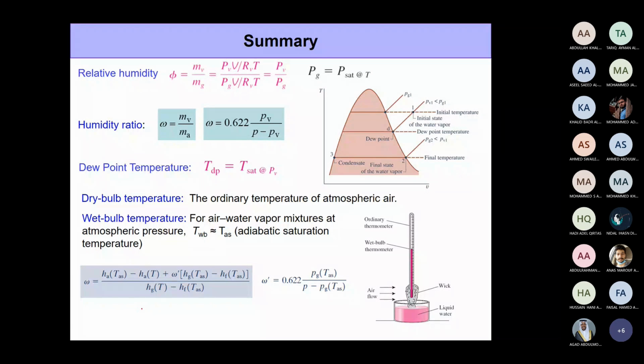So basically, the part of the water vapor that gets condensed is the water vapor or the air that is the moisture just surrounding, let's say, the glass of cold water, right? If you measure right there, then yes, some of it gets condensed, and the part that is getting condensed and the air around it is going to be at the saturated vapor state. But if I measure somewhere else a little bit away, then it's going to give whatever the relative humidity is, 83% or whatever it is. So yes, that's a very good point.